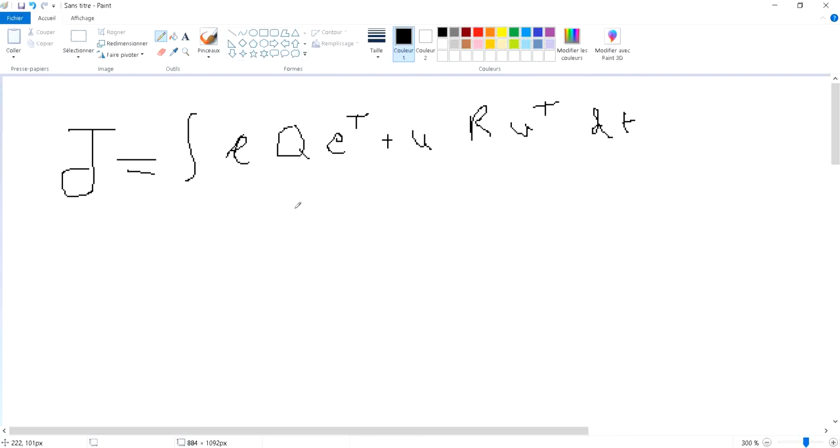And in fact, if you want to optimize the controller in order to get the best error tracking performance, what you should do is put your R, let's consider that Q and R are scalars, so you put R equal to 0 and you put Q equal to 1, and then you can say that the controller that in simulation will record the minimum J will be my optimized controller.